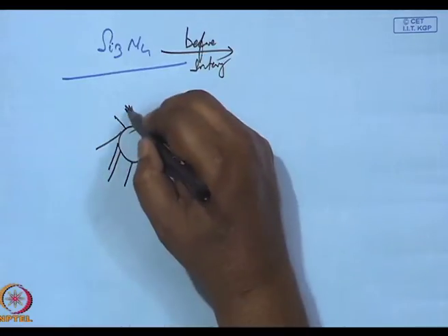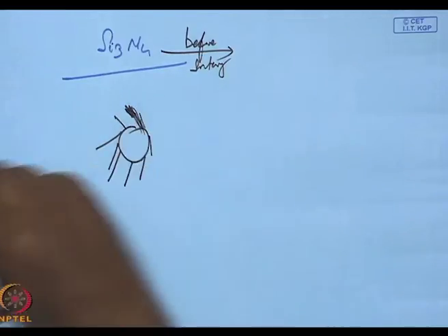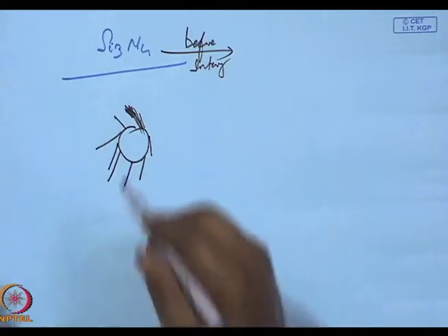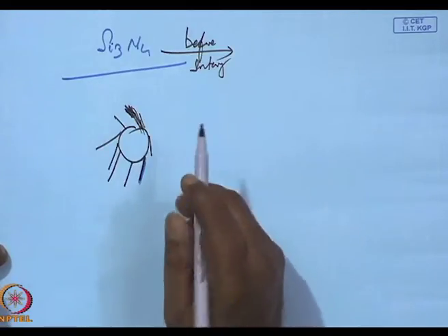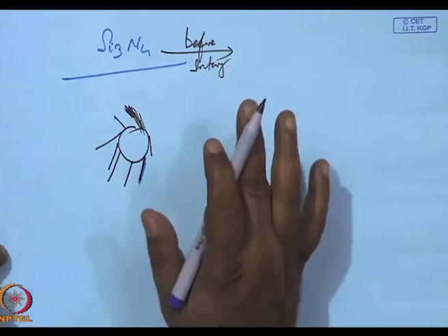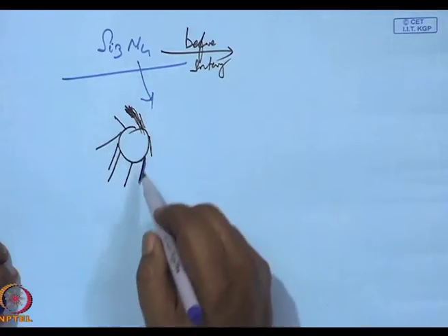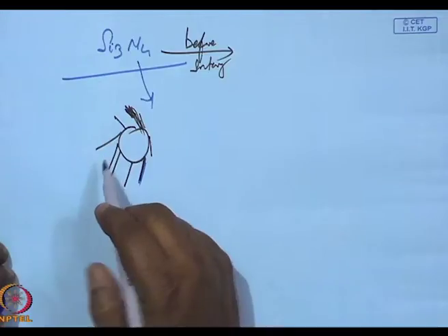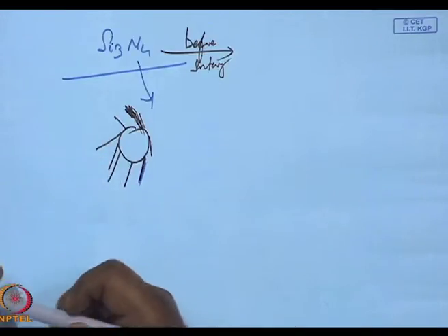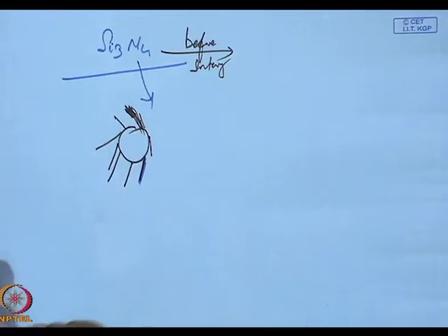Now, this silica sol covers each of the blades, and during heating the silica sol melts, sticks to the surface and prevents aerial oxidation of silicon nitride, which would have occurred if the silica sol had not been used. After sintering, the silica sol is just sandblasted away.